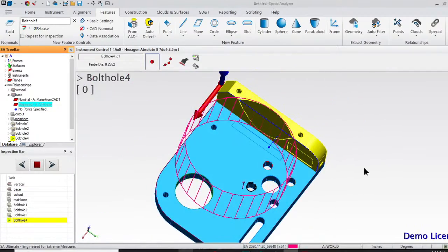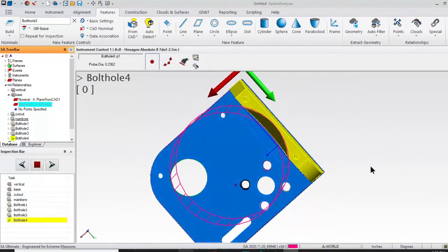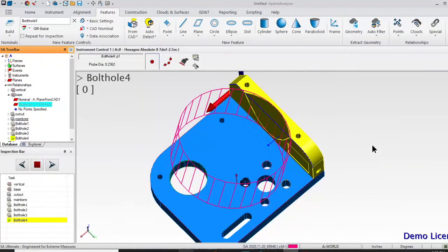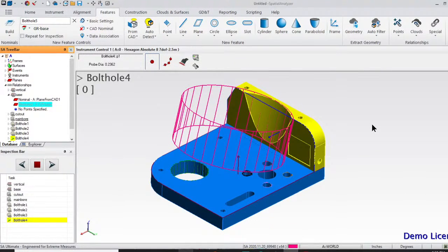All right, and then again, we could set up some dimensions. For time's sake here, we're going to skip that. We went through those steps already. So right now it's ready to trap data just one at a time. If we hover over this right-hand arrow, we see this right click is selected multi-feature scan. So what that means is we can scan into each of those features at once, and it's going to use proximity to assign data to each of those features.